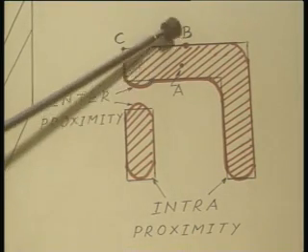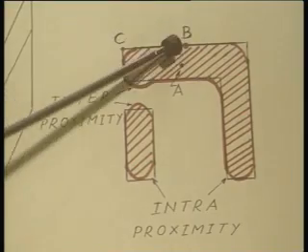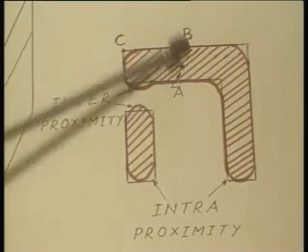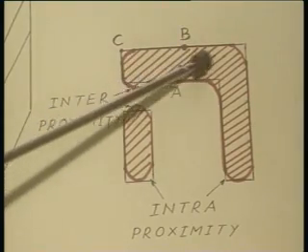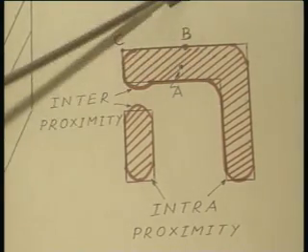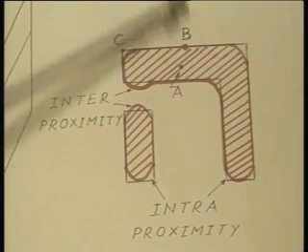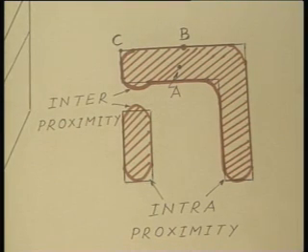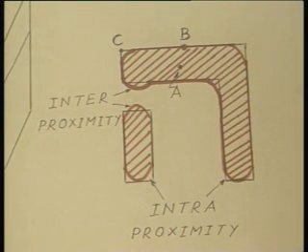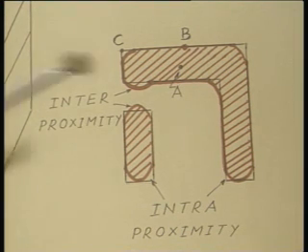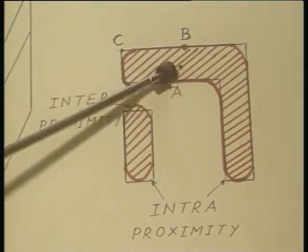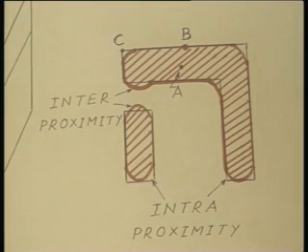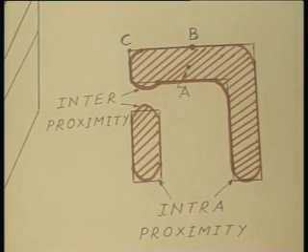Compare this with point B. Only points which are lying on this side of point B receive the E-beam irradiation, whereas all the points lying on the other side of point B do not receive the E-beam radiation. Therefore, in effect point B is receiving only half of the total E-beam radiation that is received by point A.